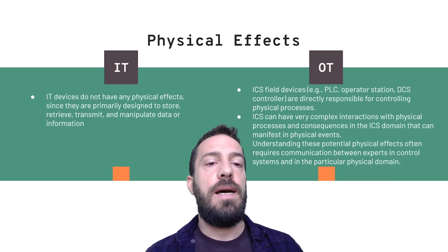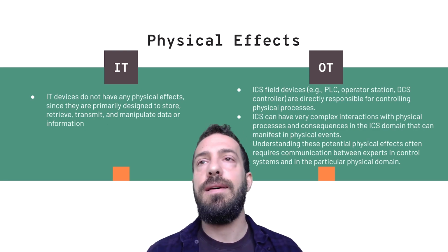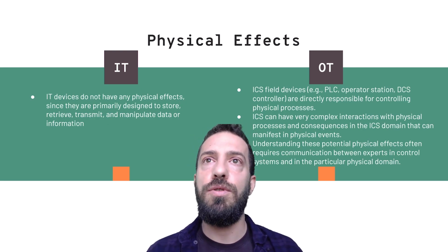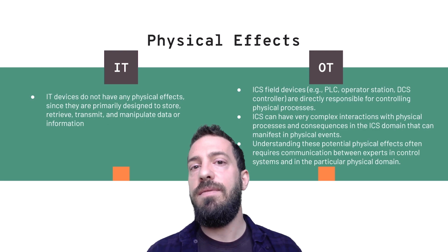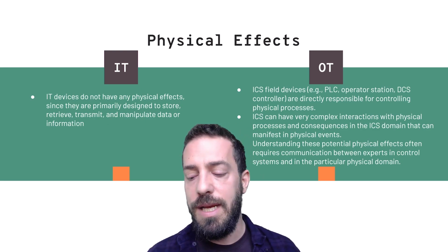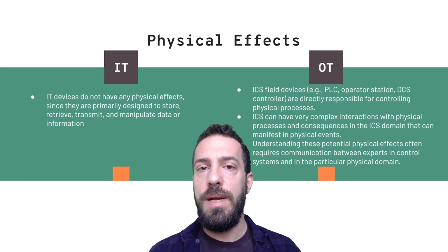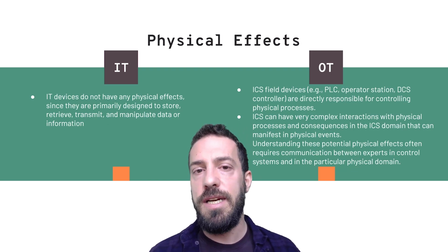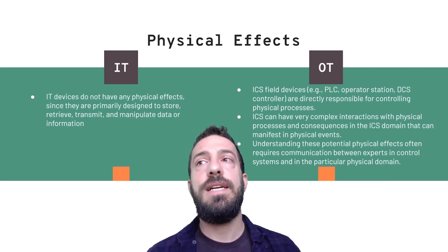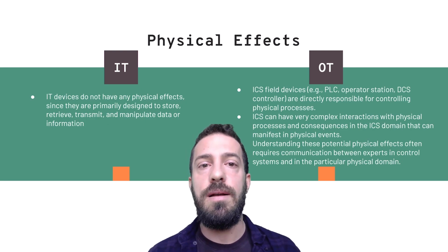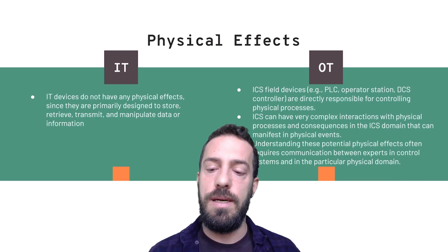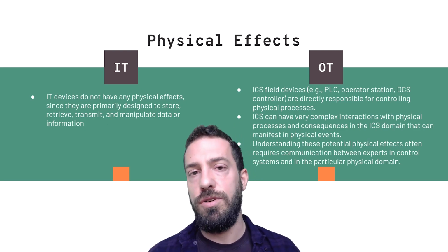So when you do security and you detect some kind of malicious behavior, then maybe your acceptable action would be to disconnect the PLC, if your control expert gave you the information you need, that it's better for the PLC not to be responding and let the process inertia take care of the rest. Then you disconnect. If the process engineer said that the PLC has to respond one way or another because stalling is unacceptable, then you take that into account when approaching the security problem and finding solutions for that.